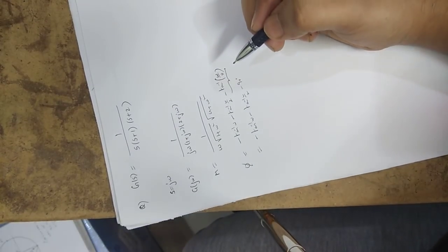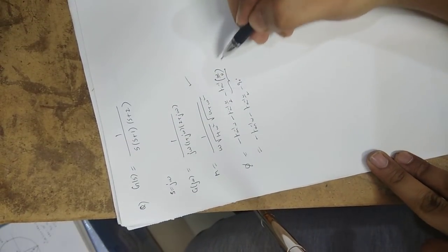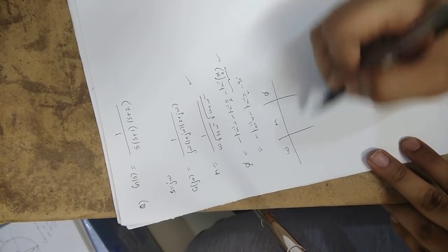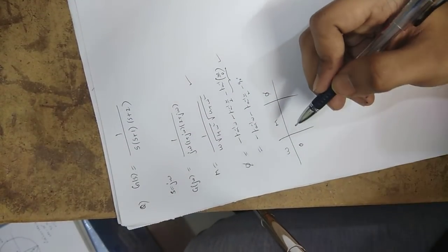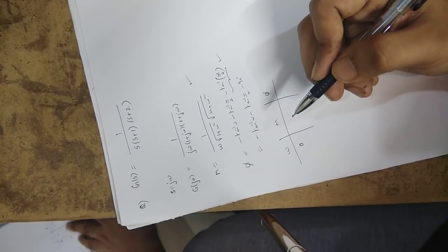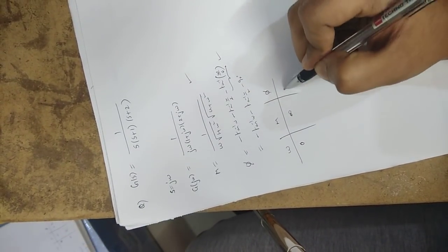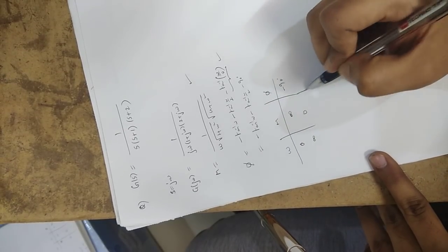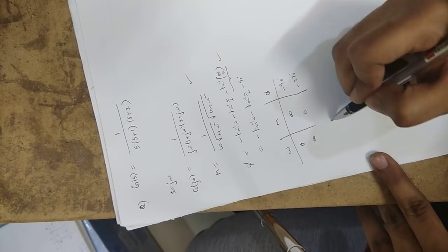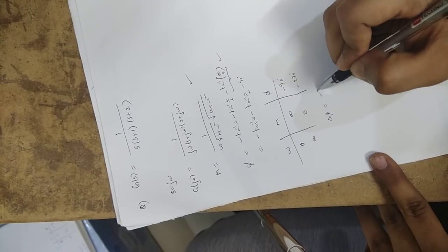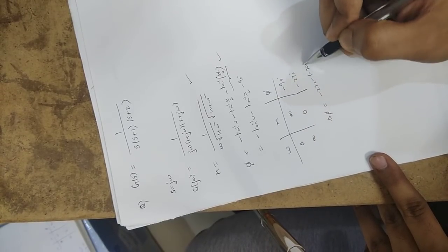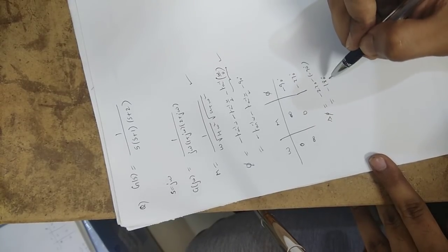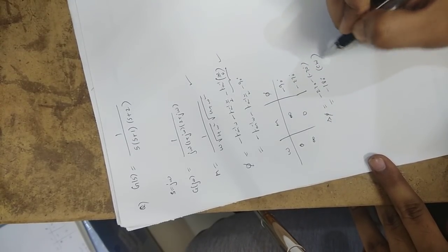So now we have the magnitude expression and phase expression; we find the magnitude and phase at the values of omega. At omega 0, magnitude is infinity, phase is minus 90 degrees. At omega infinity, magnitude is 0, phase is minus 270 degrees. Phase difference delta phi is equal to minus 270 minus 90. You will get minus 180. So the phase difference is negative, the direction is clockwise.